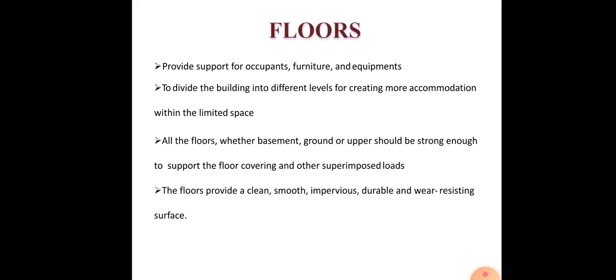The main function of the floor is to give support to the occupants, the furniture and the equipment of the building. And the other requirements include that the floor should be very strong to carry the load safely. It should provide a clean, smooth and durable surface. It should have adequate resistance against fire, and also sufficient heat and sound insulation. So these are the requirements of a good floor.